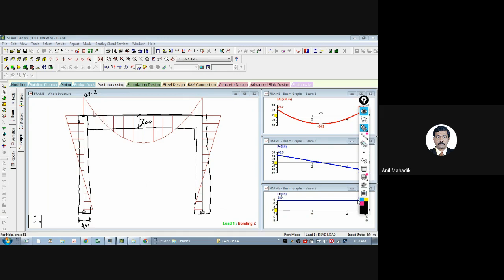That means our bending moment is important at this point. On this line, from here, the bending moment is important for me. That means this value is very important for design. This 23.2 is actually at the center, which is not real. It will come on the higher side. Understand, you get this value as 19.1, let's say. Now this 19.1, the value at the face of the column, you will get in ETABS, which is realistic. This is realistic, right?